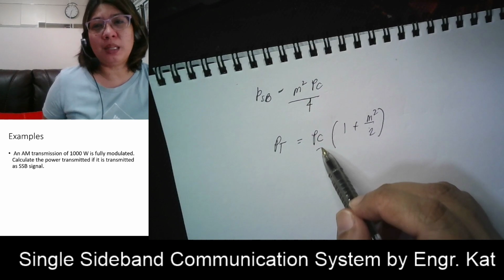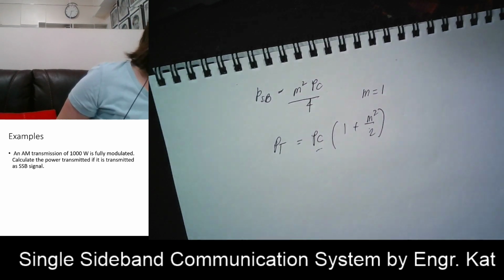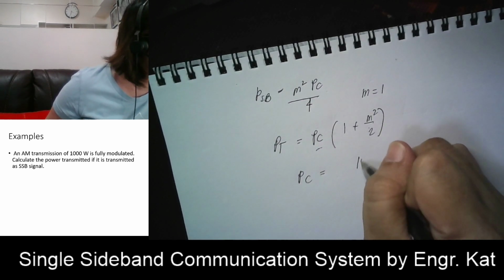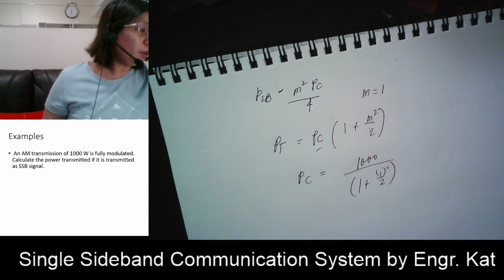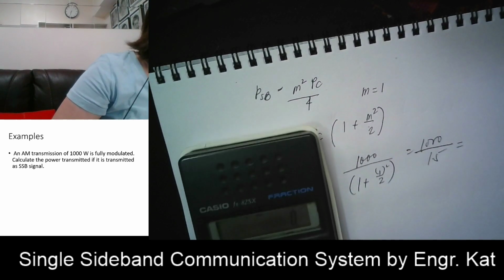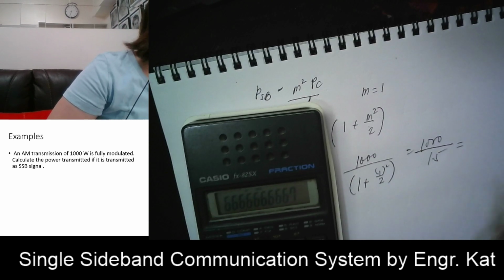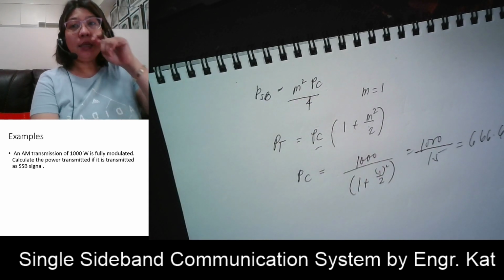Okay, so fully modulated. What do we mean by fully modulated? That is our modulation index is equivalent to 1. So that is our definition for fully modulated. So we solve for Pc. Your Pc is equivalent to 1,000 all over 1 plus 1 squared over 2. So this is equivalent to 1,000 divided by 1.5. That will give us 666.67 watts. Okay, so this is our carrier.